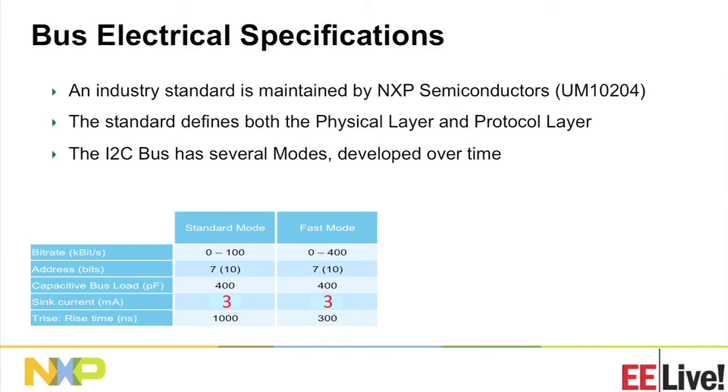If you're a computer manufacturer or a CPU manufacturer with reference designs, what you really don't want is someone to unplug a peripheral and not tell you. If you unplug a battery pack, assuming it's powered some other way, or you unplug another device that's plugged in with I2C communication, you're in trouble because you could easily hang up the bus while the processor expects that device to respond. So in the SM bus, we don't allow 0. I think it is 10 kilohertz is the minimum clock speed.